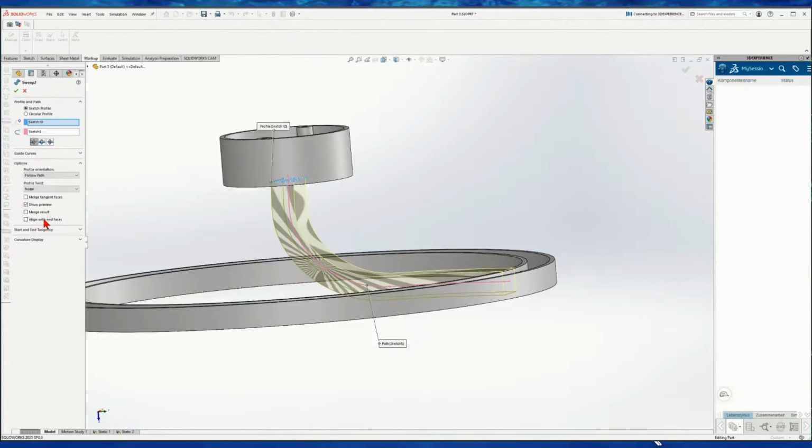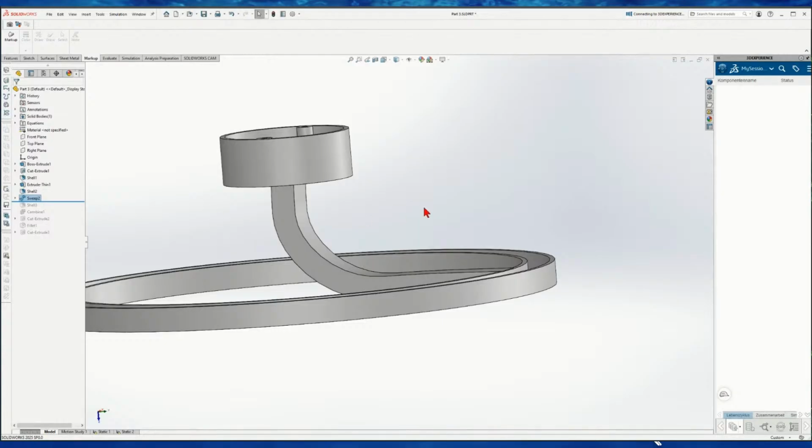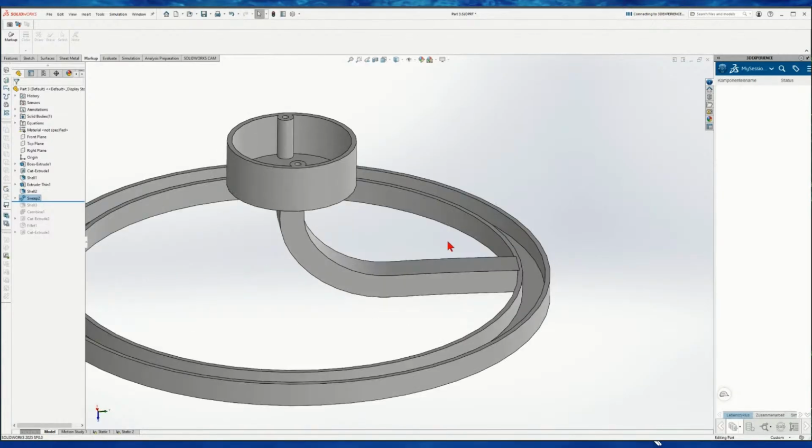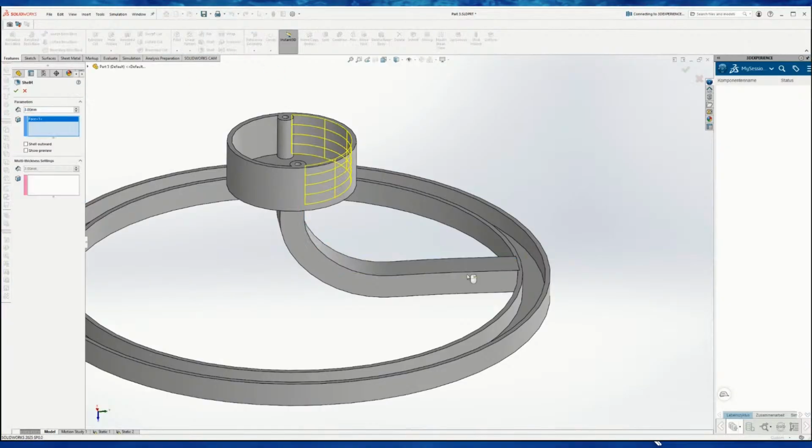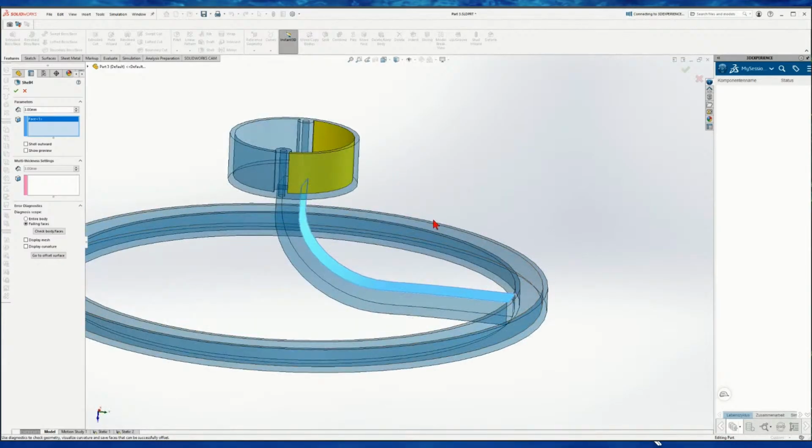By default, we have the Merge result option checked in SolidWorks. When we are working in a multi-body design mode like this, the merge result is checked, so the components actually become one. Now I have only one solid body. When I had this the first time, and I wanted to shell this, I knew it wouldn't go because we have all the other components already shelled out.